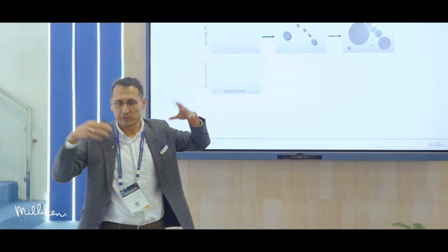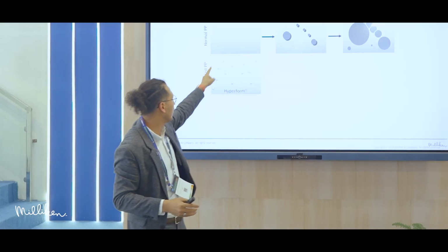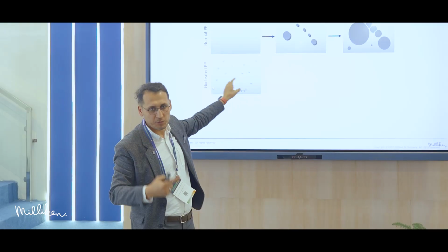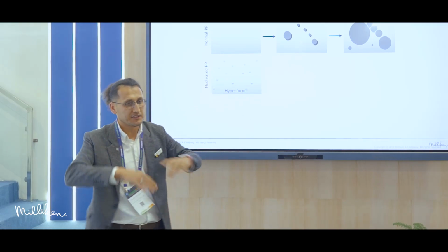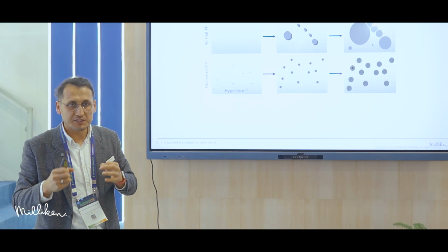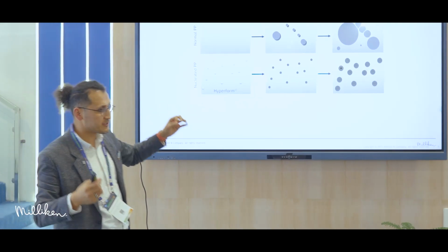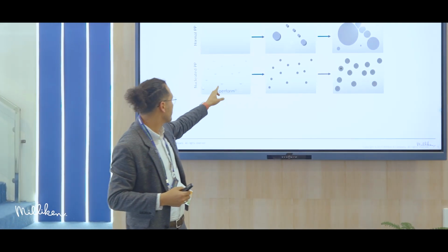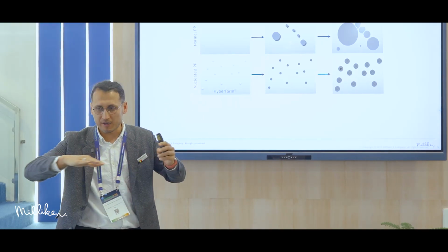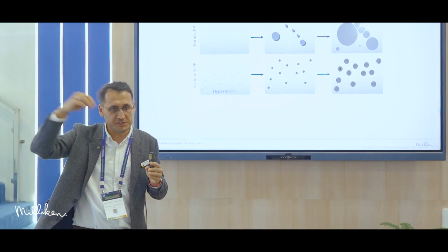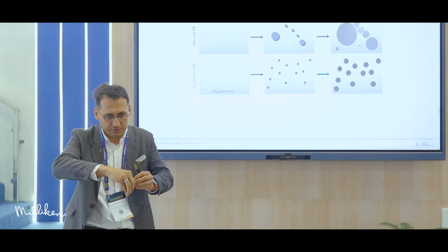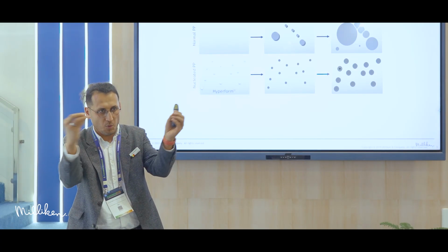This is for the illustration, but in reality, in a small area like this, perhaps you find one nucleator particle, not this much, right? But then how the nucleator helps the crystal grow is the crystal will start to grow just around our nucleators, just around that particle. It will be a platform for the crystal to start to grow. It's like we have the seed, and then the tree starts to grow from that point.